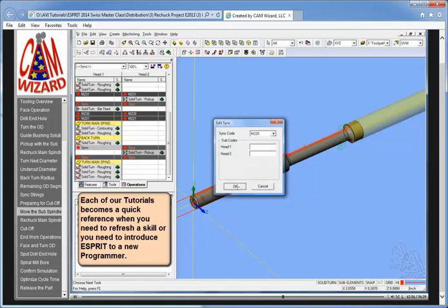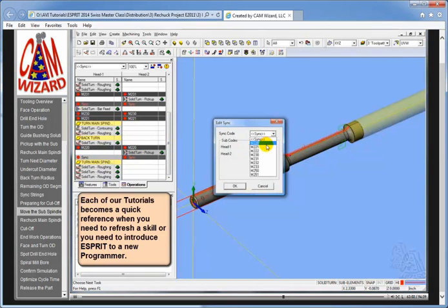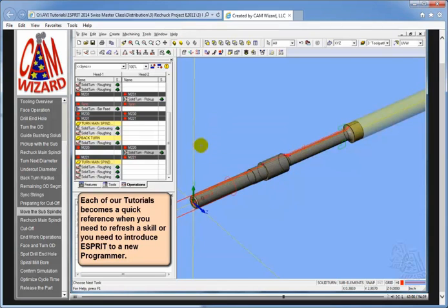So now we're not going to do synchronous turning to do our pickup. But once we do the pickup, we're going to turn it back on. Again, your machine may not require this, but it's important for you to know how to do these sync strings for those types of unique instances of how you need to control your syncs and to do other auxiliary things, like in this case turning on and off synchronous turning using both spindles.